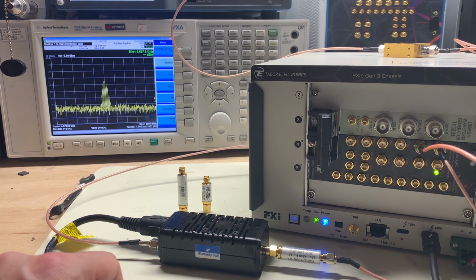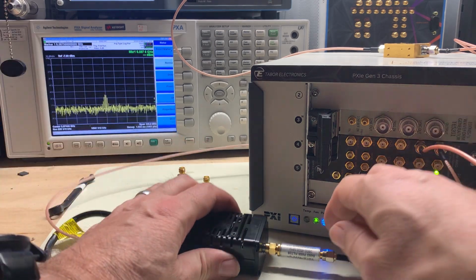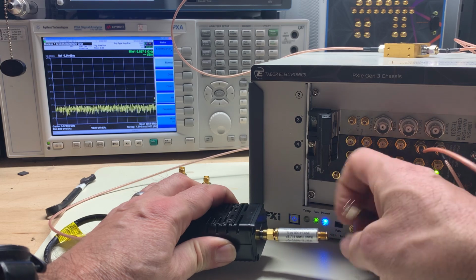Now another way that we can change the frequency is to use the internal IQ modulator. First of all, I'm going to do a 1.5 gigahertz AM modulation. So I'm going to take that pulse and modulate it on a 1.5 gigahertz carrier. If I do that, we step up in frequency by 1.5 gigahertz, to 5.574, and you can see that we've got the carrier there, 5.574. Amplitude's low though, so this rolls off at 4.5 gigahertz.